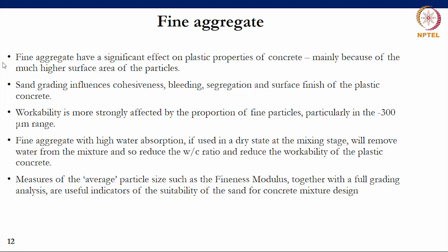Let's turn now to fine aggregate and think of the sand fraction of aggregate in concrete. Fine aggregates have a very, very large effect on the plastic properties of concrete. This is mainly because of the much higher surface area of the particles that have been broken down, as we said, from 5 millimeter sizes down to very fine particle sizes of the sort of submicron sizes. Sand grading influences cohesiveness, bleeding, segregation, and surface finish of the plastic concrete.